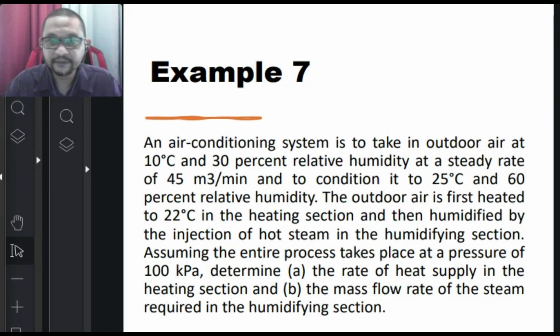The assumptions that you have to make: number one, this is a steady flow process and the mass flow rate of the dry air remains constant during the entire process. Number two, dry air and water vapor are assumed to be ideal gases. And number three, kinetic and potential energy are negligible. So that is the assumptions that you have to consider.